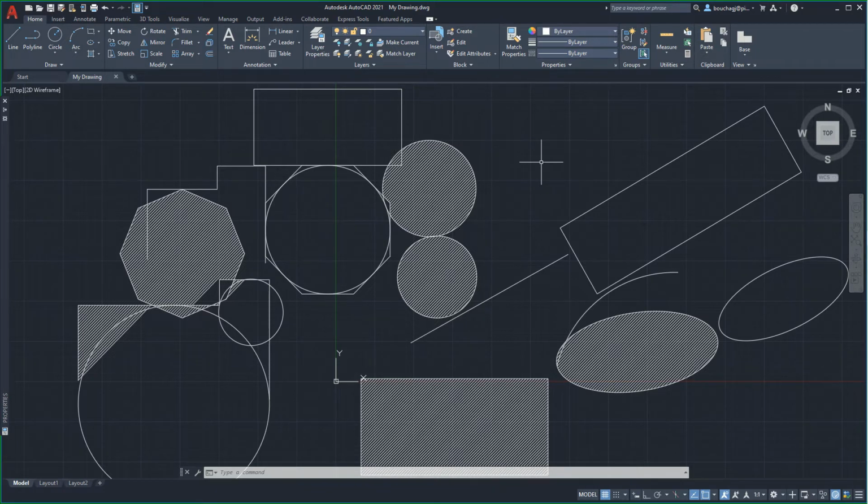If the intention is to mirror an object across the X or Y axis, having orthographic mode enabled is recommended. Let's mirror this ellipse directly to the right, a reflection across the Y axis. Enter the mirror command. Select the ellipse if it has not been previously selected. The next command line prompt asks the user to specify the first point of the mirror line.